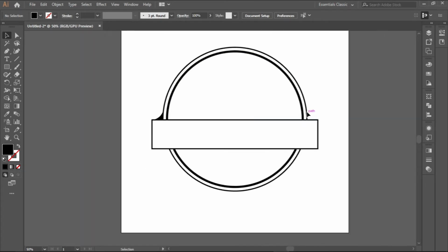We want to make the same exact one here. Since this angle and this angle are the same, we don't need to redraw it. We can just copy this one to that side too. To do that, you click on Alt and then move it holding Shift. So that's Alt and Shift together to copy it to the other side.